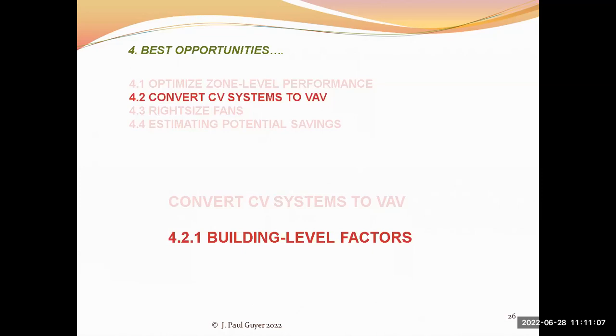But if you're going to have to remove asbestos to get access to features of the air distribution system, then that's going to be a big impact on your project, because there are worker safety procedures and equipment and safety clothing that are going to be necessary, and those are all cost items. So that will run up the cost of your retrofit project.